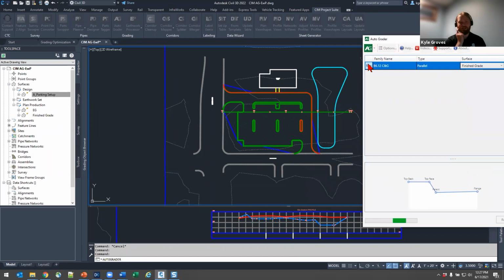The other thing is that it also goes through and knows which feature lines it created versus which feature lines the user created. So as soon as I refresh this, if I lost any of that parent line work, it's going to delete those out. It's going to scrub those out of my drawing for me. And it's always going to go through and refresh it.